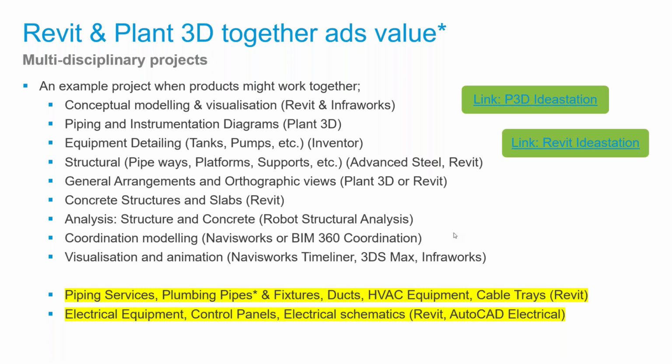So the question is how to move the files over and to do, for example, clash detection between Revit and Plant 3D. Apart from some changes in the software, which I will not talk about, that will be coming soon, the current workflow, which I think is a really good one, is to use the review function of BIM 360 to create a final review on your design before you publish it into the clash detection.